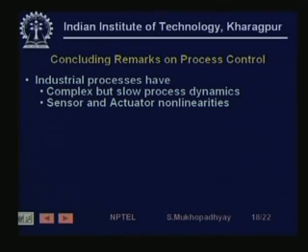They have phase lag, they have non-linearity, gains will change, so that creates complexity, but at the same time the process dynamics is slow. Sometimes that is good, in the sense that fast processes are difficult to control, but disturbances also travel slowly and they should be detected early, otherwise large errors may persist for unacceptably long times.